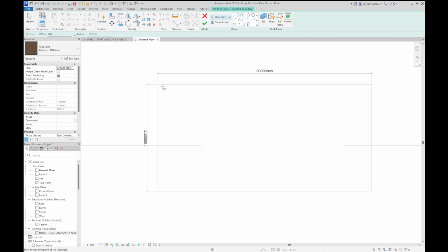So when I hover over the top left corner, you'll see a little square marker appear. That is called a snap, and what that is doing is snapping to, in this case, square means an end point. So it's found the end point of a line, which is what we want. So if I've got a snap, I'm going to be happy. So I'm going to left click,